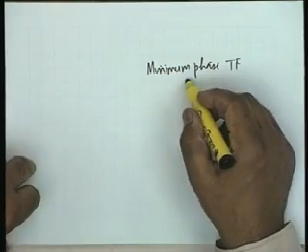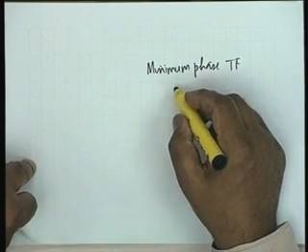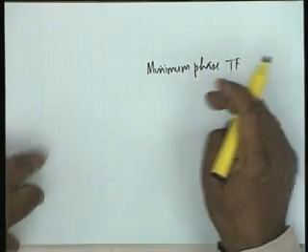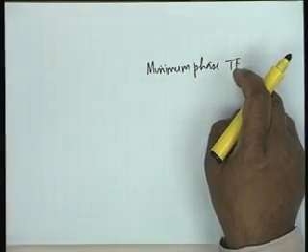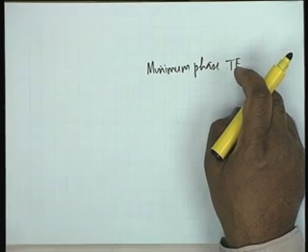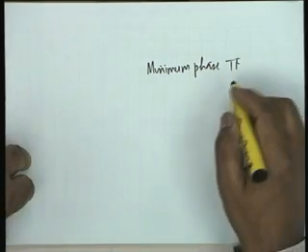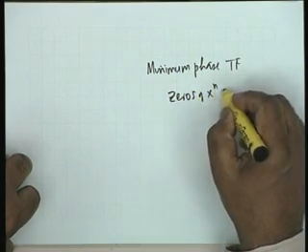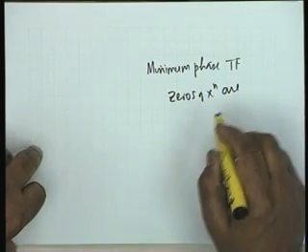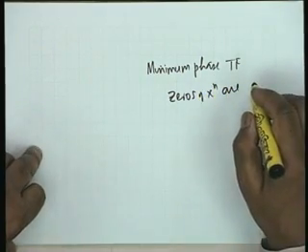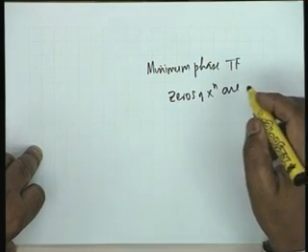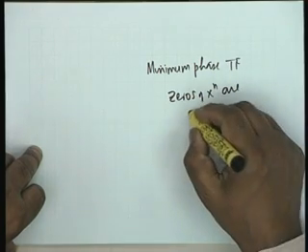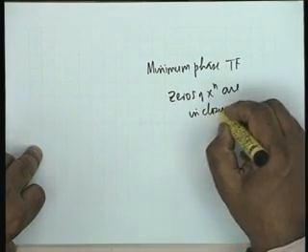A minimum phase transfer function is one in which all transfer function zeros are zeros of transmission in the open or closed left half plane. Open or closed? Closed. Are in the closed left half plane.